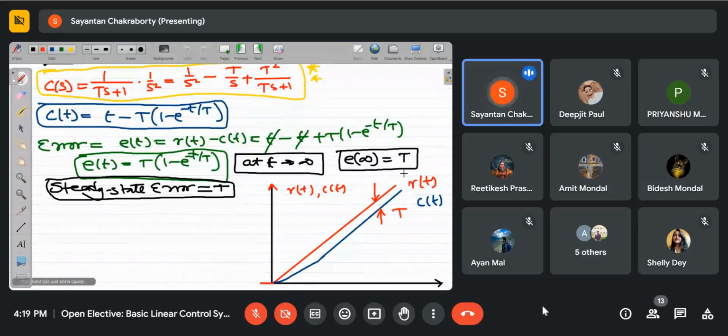Since we're more concerned about the time response in the transient region only right now, we shall only be concentrating on unit step input. But that is not all. To completely understand the time response you have to also comment on the steady state value, and for that you need to find out the steady state behavior for each and every input like ramp and impulse, okay.